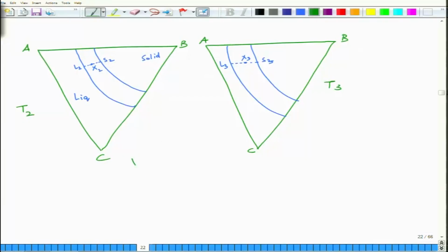So eventually as you go down to lower temperature, if you draw the cross section, you will have alloy X, which is completely solid. So this would be completely solid at this point. This thing might have moved somewhere here, but it does not matter. For this composition, for an isomorphous system, you will have complete solidification by this point.